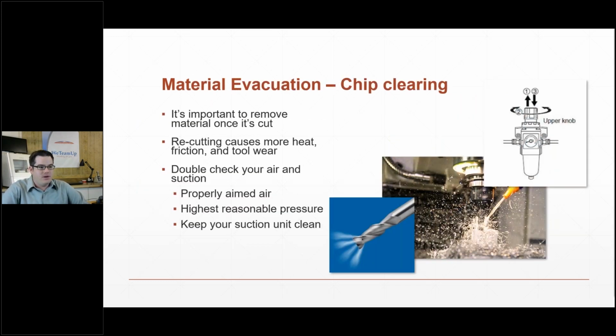And next here, material evacuation. It's pretty common to see either underfed compressed air into a machine, like the regulators turned down too low, or a clogged vacuum system. But what happens with tooling is when it cuts, you inevitably make some debris, right?